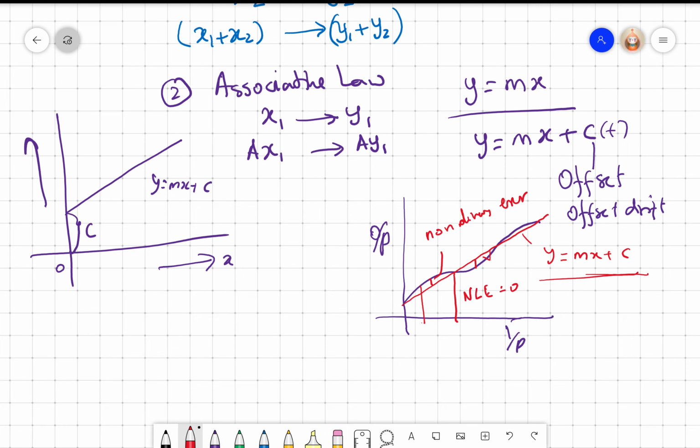So sometimes manufacturers give you this curve and also give you the linear fit, right? And specify what is the offset and what is the slope. The slope is also known as the sensitivity because it's delta V naught by delta V in, right? The slope of a straight line is delta y by delta x, and hence the slope is the sensitivity of the transducer. But in many cases it may not be possible for the transducer to give you the curve that is given in the violet color, right?